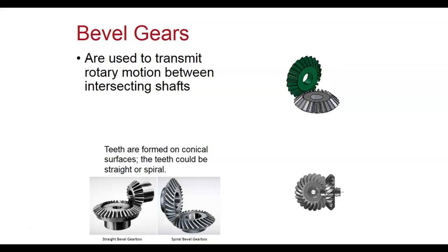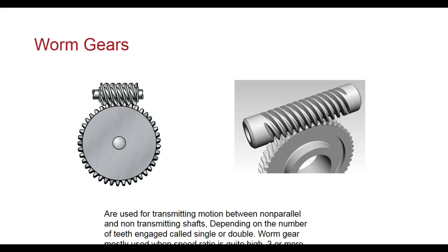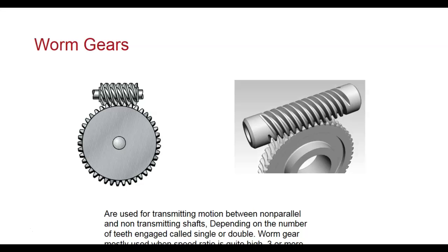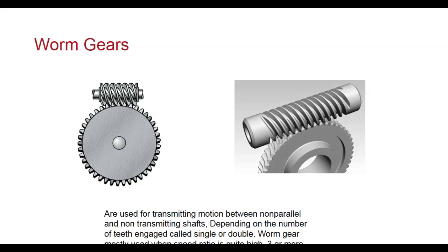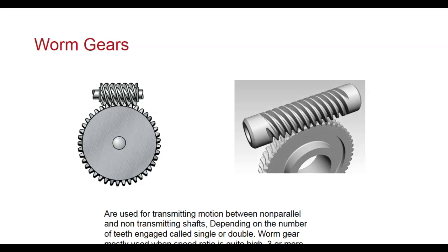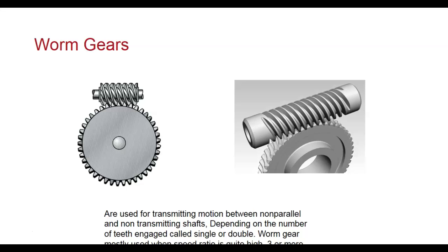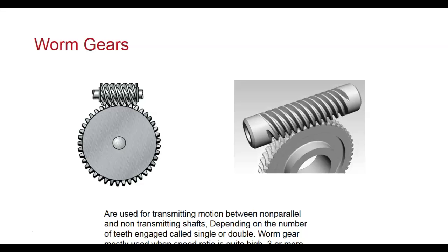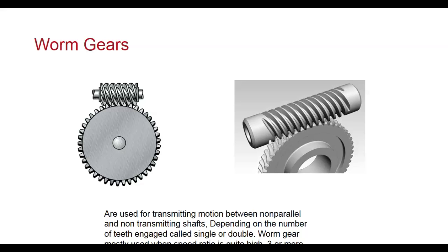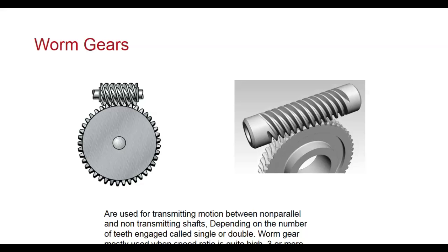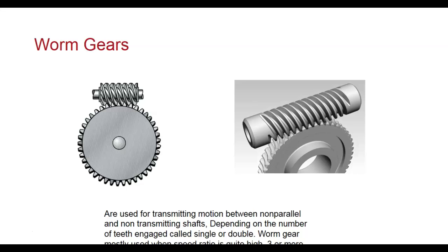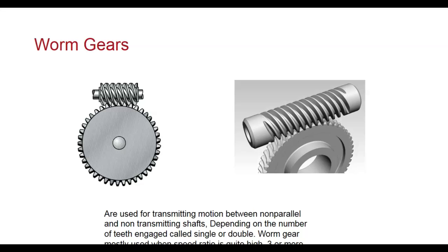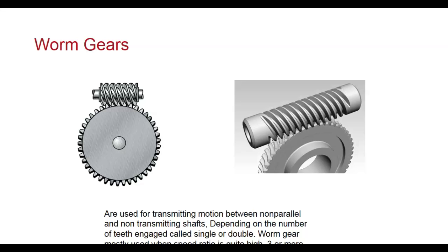We okay? I don't know if we got any of these or not. This is called a worm gear. These usually have a really big ratio between the driver and the driven. This one right here is usually real big and this is real small. This is the one that he was showing on the video, where it took, I forgot, like 40 turns to make one revolution.